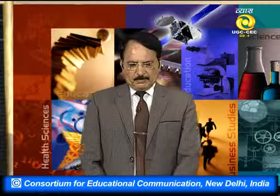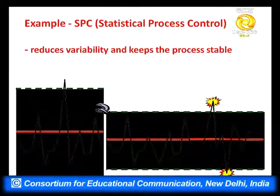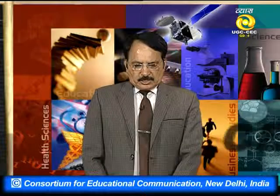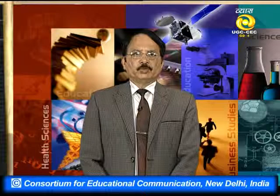And this is one example of SPC, Statistical Process Control, which reduces variability and keeps the process stable. And this is a control chart. Disturbed process, the left one: the drawing shown on the left side shows that the process conditions are beyond the upper limit. It means the process is disturbed at this particular point and some action is to be taken. Similarly, on the right hand side, there are two occasions when the graph is going out of the specifications. The first one goes above the upper control limit, and the second goes below the lower control limit.